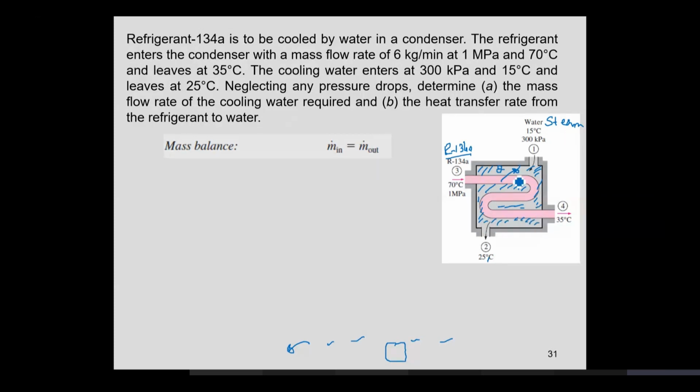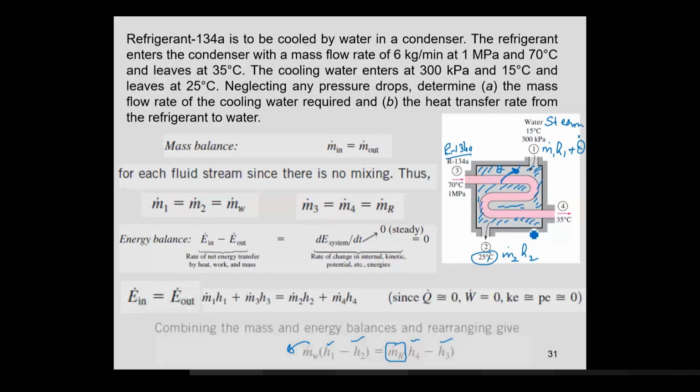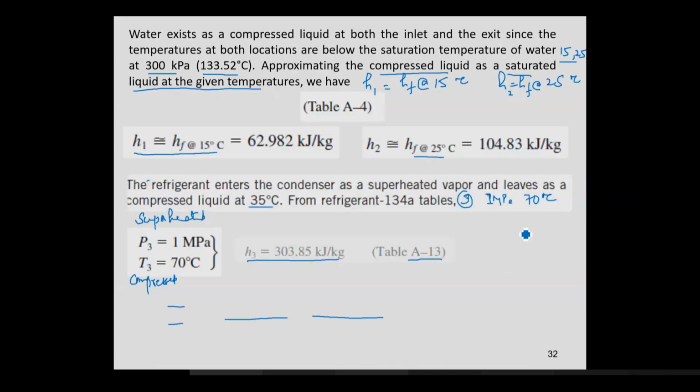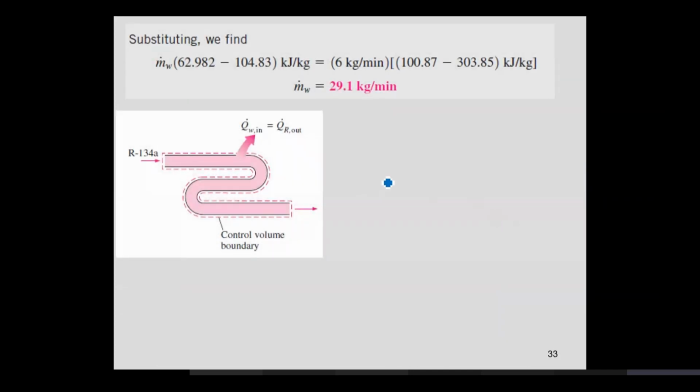If you look at this control volume, there is heat transfer moving into the system. There is energy entering the system in terms of mass flow rate, so there is m dot h1 entering the system, and heat, Q dot, entering the system. The energy leaving is the energy of the fluid leaving the system, which is m dot h2. So you'll have a modified equation,